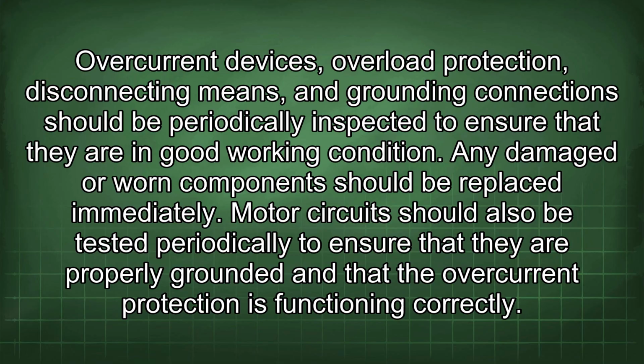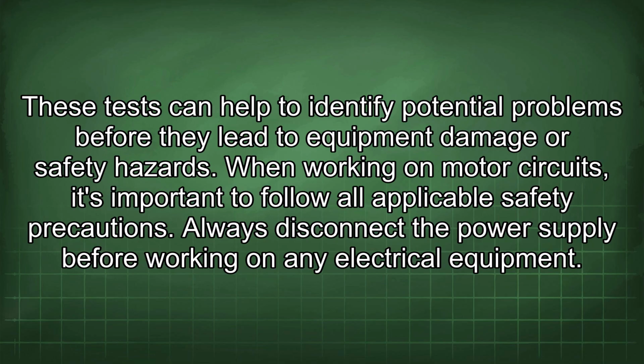Motor circuits should also be tested periodically to ensure that they are properly grounded and that the overcurrent protection is functioning correctly. These tests can help to identify potential problems before they lead to equipment damage or safety hazards. When working on motor circuits, it's important to follow all applicable safety precautions. Always disconnect the power supply before working on any electrical equipment.